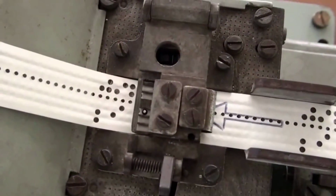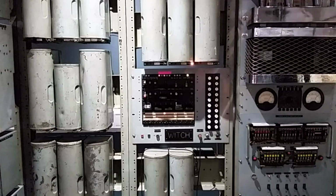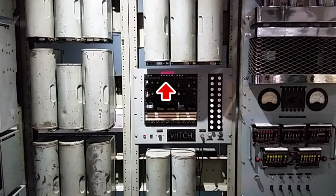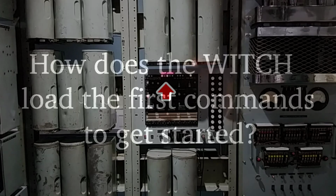Because the paper tape system utilizes 5 bits, the input system is also designed around 5 bits and is generally referred to as the 5-wire input system. Decoded characters are then transferred to the storage registers or loaded as commands to be executed.